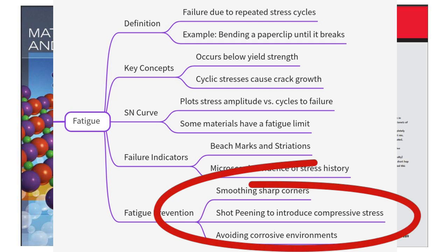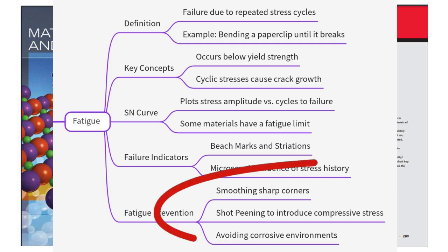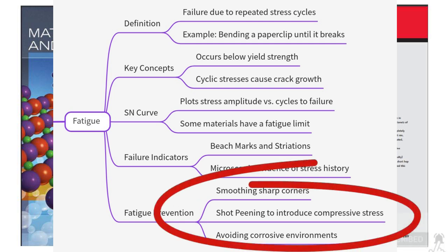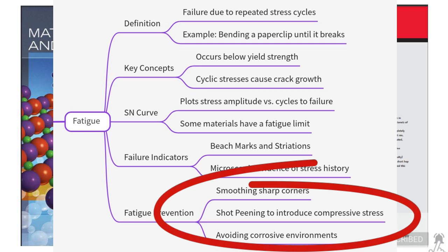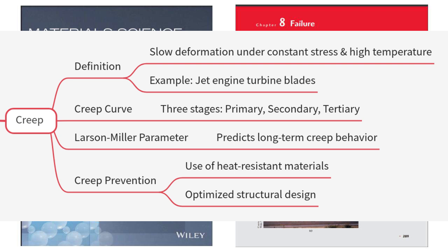And then you have things like surface treatments, like shot peening. Shot peening's a really cool process. What is that? You're basically bombarding the surface with tiny little beads to create compressive stresses in the surface. What does that do? That actually makes the material more resistant to crack formation. So it's kind of like giving it a protective shield to deflect those stresses. That's a great analogy. Exactly.